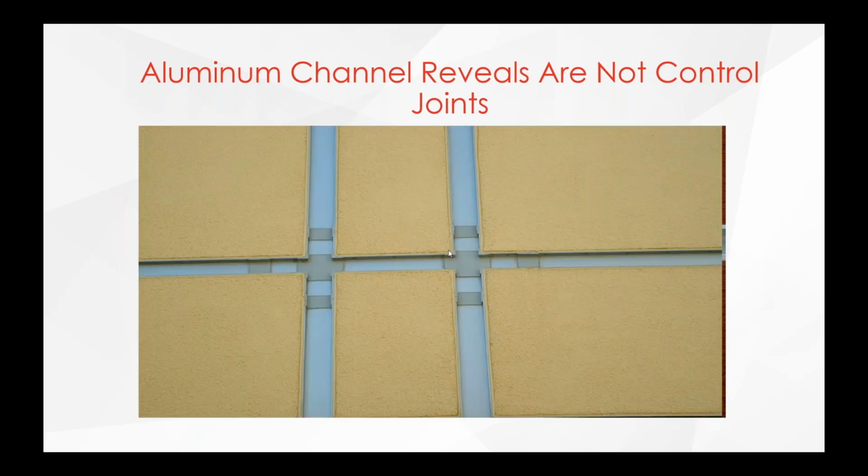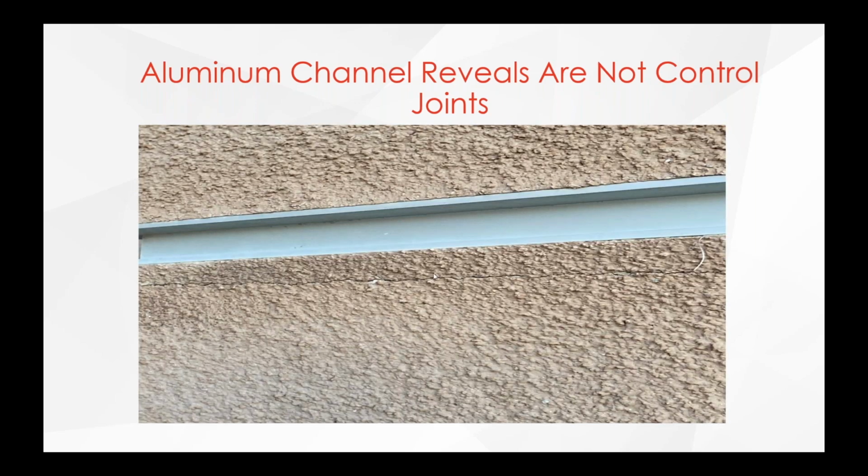So you might be thinking, what's the fix? This is the fix. Not too pretty looking. This was a job in the Bay Area. It was a hospital, and before the hospital interior was completed, I think they counted up 400 separate leaks. They found out it was coming through here, so this is what they did. They routed the stucco out here, they filled it in with a sealant, and they put an elastomeric coating on it, and 1, 2, 3 tape over all of these. Again, not a pretty look, but that's what they had to do.